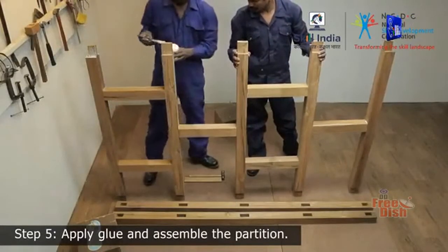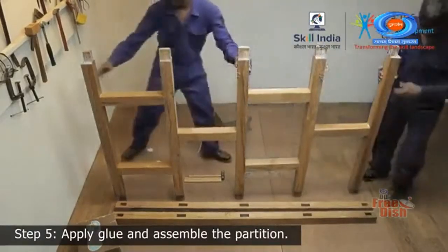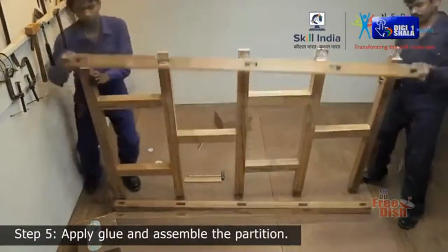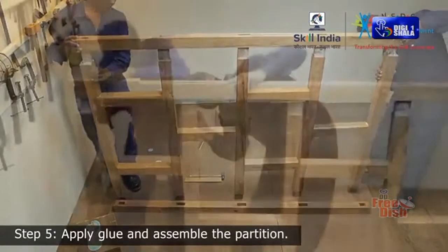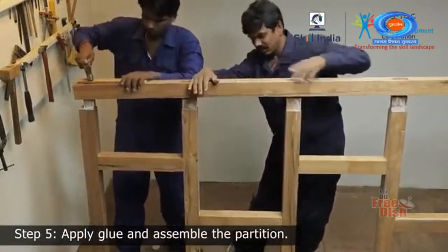Apply glue onto the tenon on the top side of the studs and place the bottom rail on top of it, and tap the bottom rail lightly with a hammer till it fully sets in.